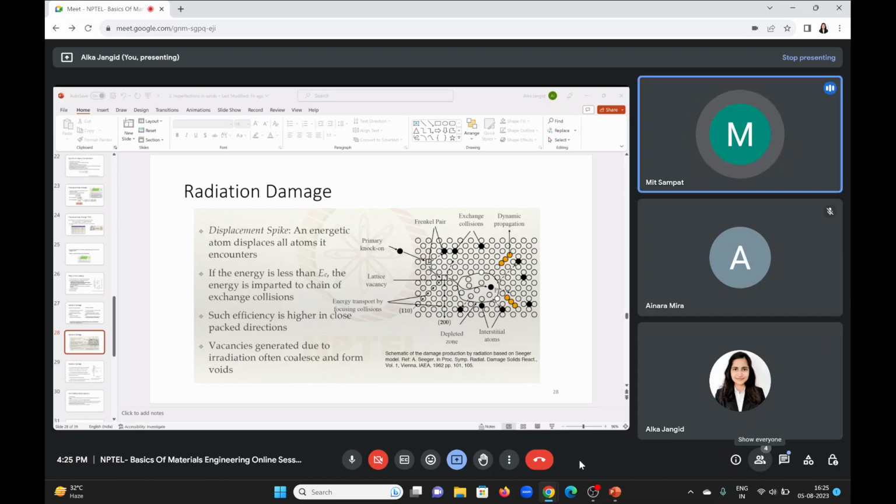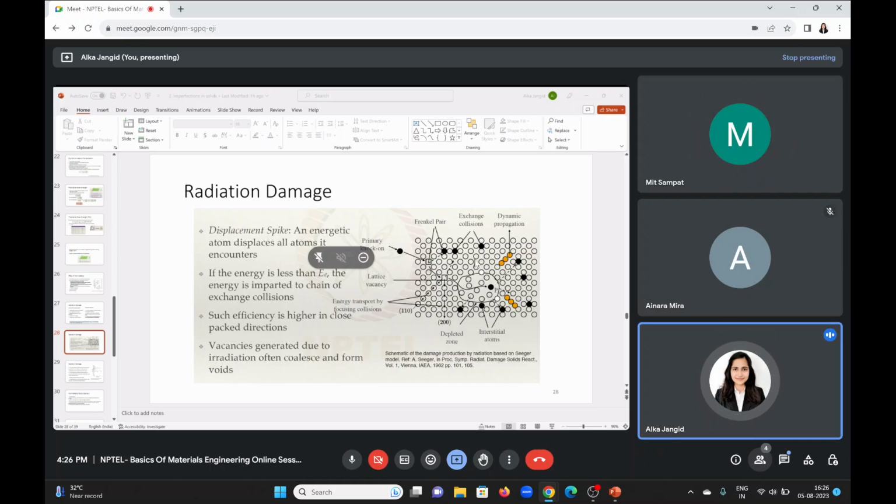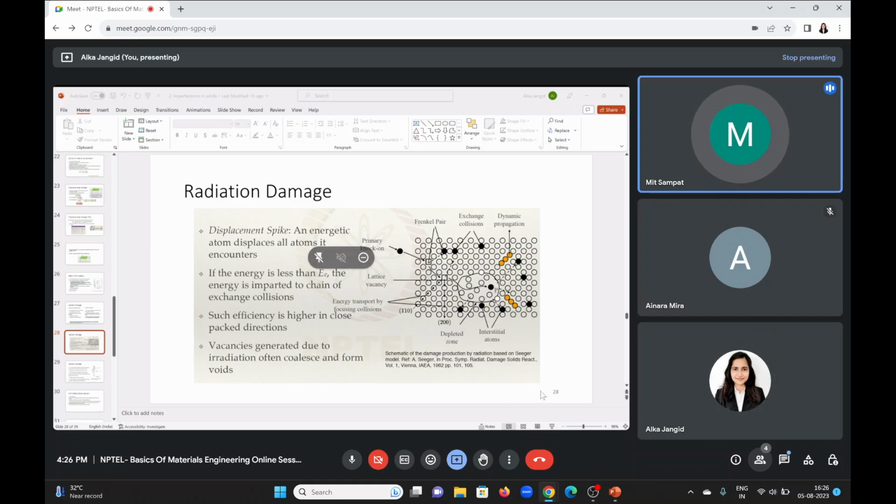Yeah, actually, I recall that sir told us about polycrystalline material. In polycrystalline material, these effects get nullified. Even if we apply force in different directions, we will get the same tensile strength for a polycrystalline material. Because in polycrystalline materials, some of your grains will be oriented in the slip direction, and some won't be. So it will nullify the effect of direction.